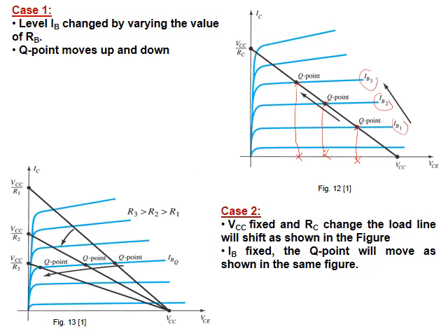This is one view. Another view: what happens if we change R base, R collector? We change this so that, rather than R1, it becomes R2, then R3. You see, we are increasing R. We can see that this point will move from up to down, and based on this, the quiescent point again moves to the left, almost linearly, and VCEQ will also move to the left, meaning it gets reduced. This is another picture we need to put aside.